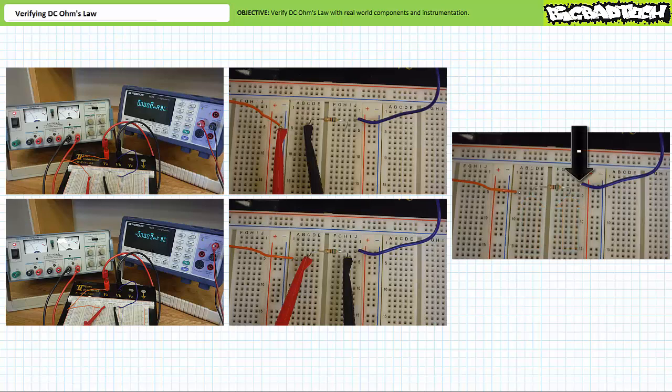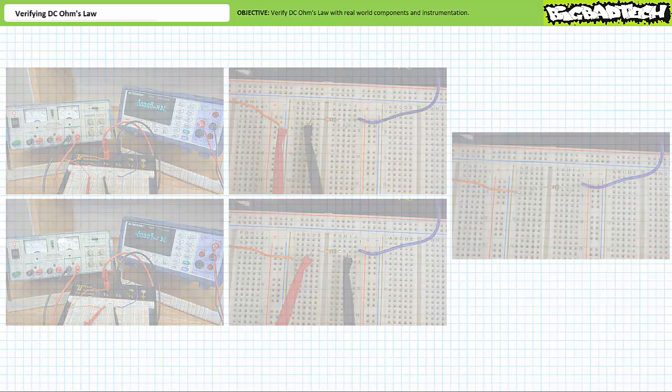However, the negative terminal of the source is landed at node 3F through J. No connection exists between node 5F through J and node 3F through J above it, and no path for current exists. This is an open, and no current will flow through this circuit, nor will any voltage be dropped across the resistor. Close visual inspection of the circuit has identified the problem.